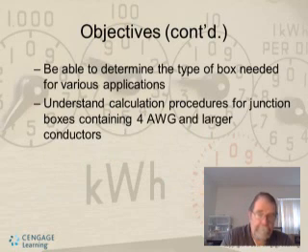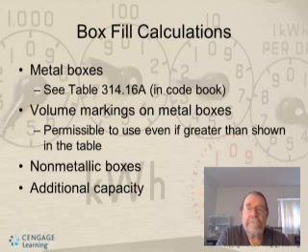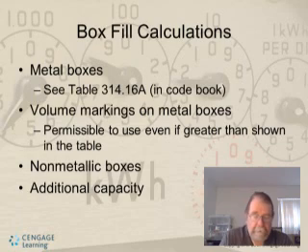And then also you'll need to be able to determine the type of box needed for various applications, understand calculation procedures for junction boxes, 4 gauge and larger conductors. You need to basically do box fill calculations.